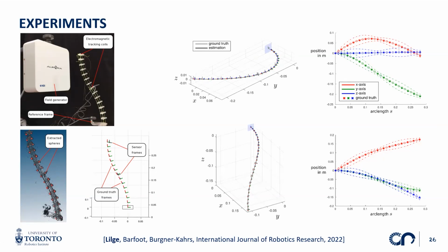We use a secondary, another measuring technique. Usually you want to use a sensing technique that is quite accurate. In our case, we are using a point cloud of the robot. It's not shown here, but we have a measurement arm, a passive robotic arm with a laser scanner attached, and you can move that around in 3D space.